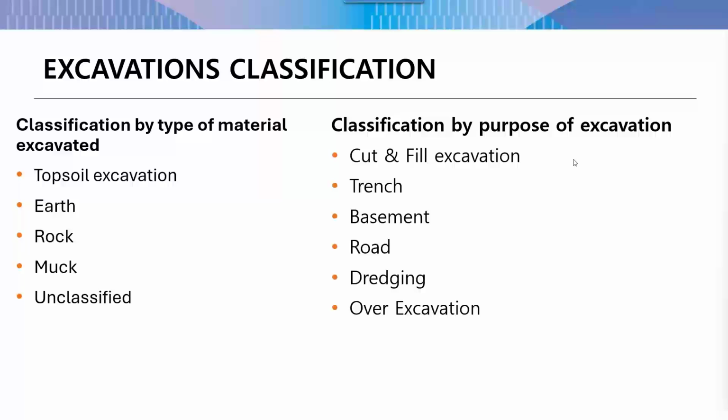Muck excavation is done where the water level is quite high and the soil is of horrible quality, so the material cannot be reused for anything and has to be dumped somewhere. It is like excavating clay, highly cohesive soil or silt. And then some can also be termed unclassified types.